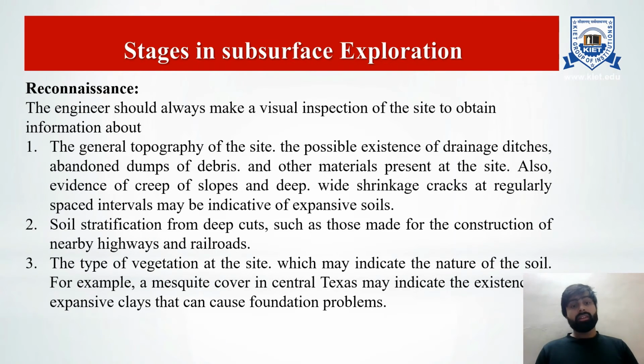Reconnaissance: the engineer should always make a visual inspection of the site to obtain information about the general topography of the site, the possible existence of drainage ditches, abandoned dumps or debris, and other material present at the site.